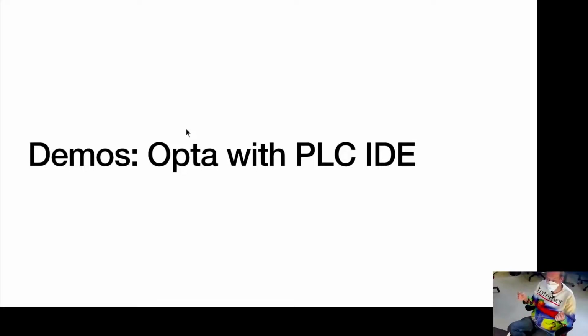I don't know if I'm answering the same question you asked. So the relays here are incredibly useful because you could switch mains powered lamps or motors or whatever else. If you want to switch something at a high frequency and vary its intensity like you would with PWM, then a relay output is the wrong choice. There are other outputs that I'll talk to later that allow you to do that. Unfortunately, with this Arduino PLC, that's not a straightforward thing to include. So I'll also talk about how you can expand this for more input-output options.